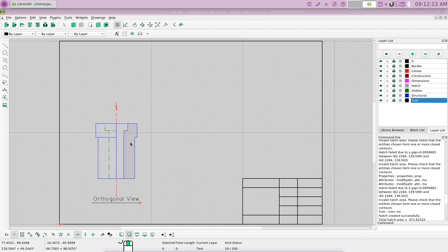Okay, now to use these lines, we're going to extend them up into this area. They will form the perimeter of our top. And they're going to be construction lines. So let's make sure we're on the construction line layer. And let's make sure that we're on end snap.